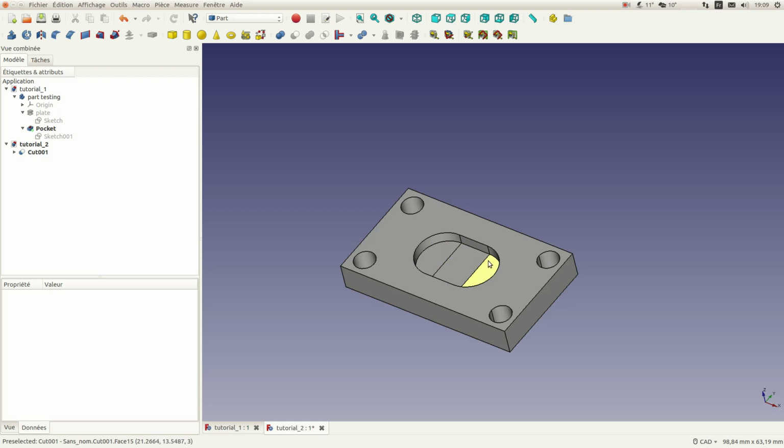And when you are a machinist or CNC machinist, it's very easy for you to understand that when you want to make a hole, you have to create a drill. The drill is a cylinder, and then you have to apply to the material. And for a pocket, for example, it's like EDM. You create the die of the EDM. You select the dips of the things, and then you just have to subtract the main part from the die of EDM, and you have the result.